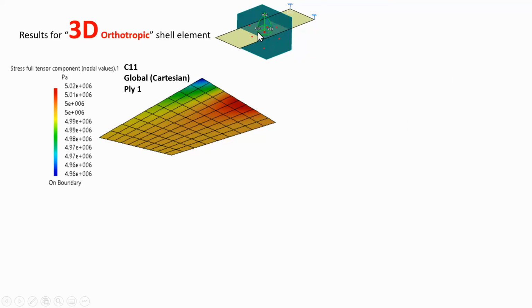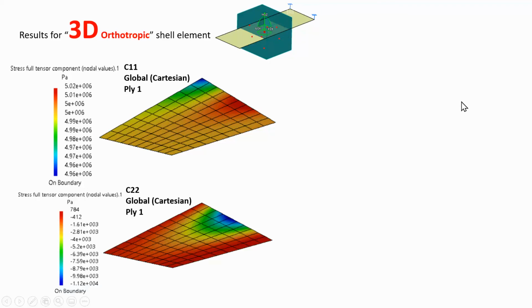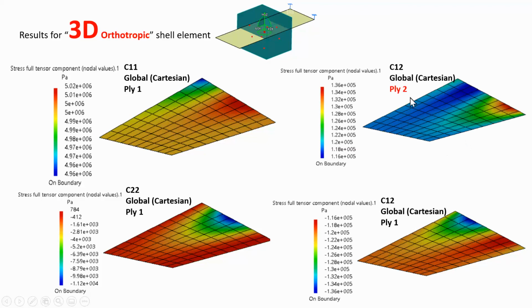And so I'm looking only at the stress in this corner, because at the ends we have end effects, because here you're clamping things. So exactly this clamping affects the stress distribution there. Anyway, I look at this section C11, C22, and torsion. Even for ply 2, these were all ply 1, except for one of them I did for ply 2.